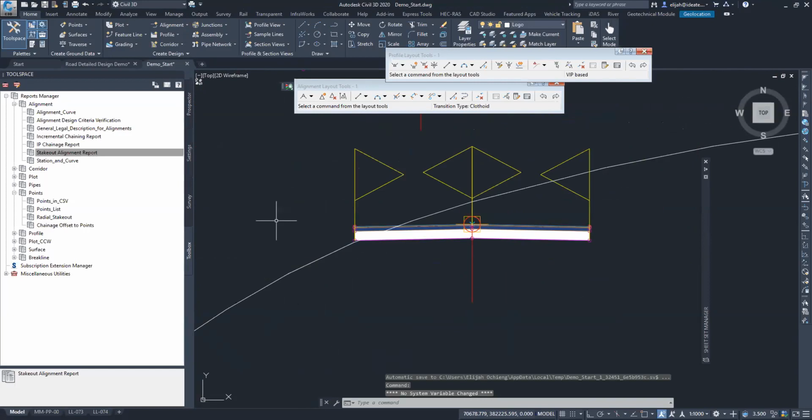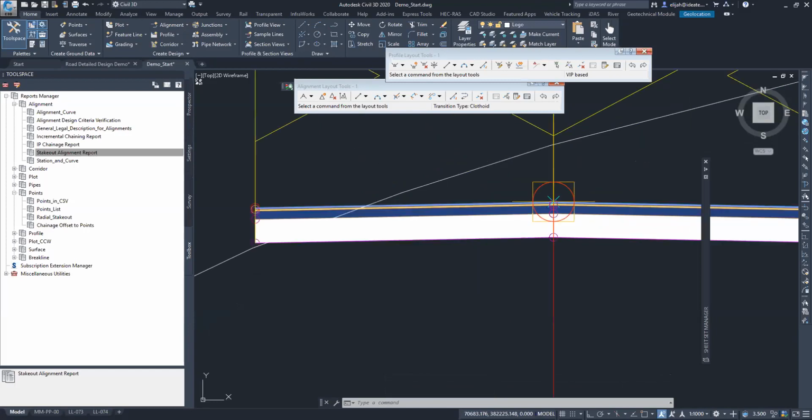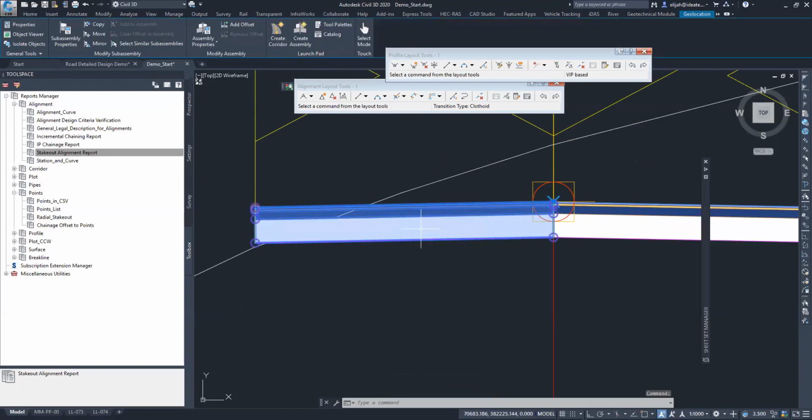Like if from the pavement design you got that maybe the subbase was 200 or 300, you can now start customizing and choosing those specific values for the assembly, as you can see on what I'm showing on the screen. So you can only do geometry design for the road and the section design plus a corridor design, then do your earthwork volume and generate setting out data, but you can't do pavement structure design.